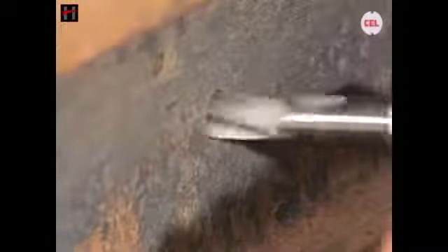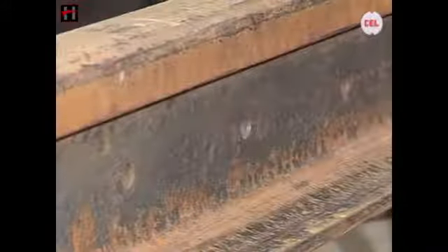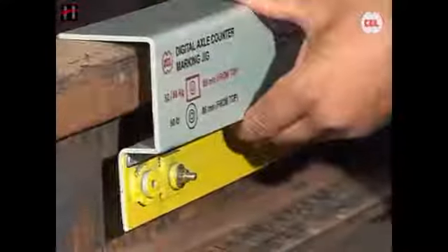Use ratchet or drilling machine for drilling the hole. First, for drilling the hole, use drill bit of size 6 mm or 8 mm. Then use drill bit of 14 mm size for drilling of web as required. Drilling is done manually, but it can also be done using an electric drill machine like this. Verify the position of holes by fixing the marking jig with clamp properly.